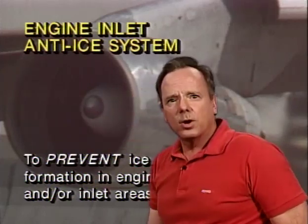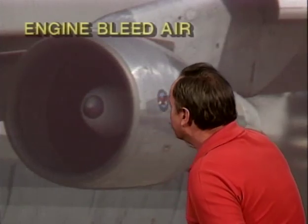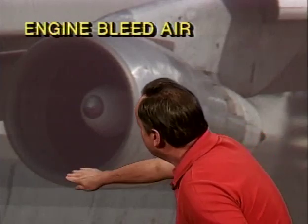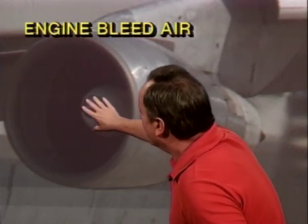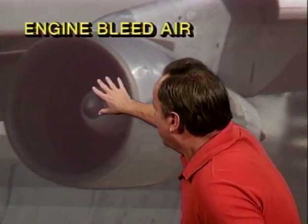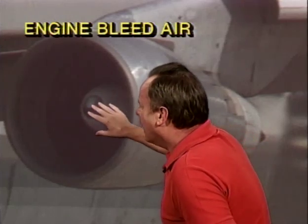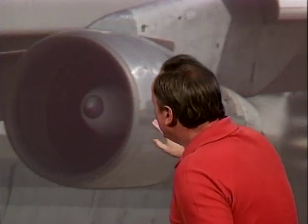Now, how does this work? Well, normally anti-icing of jet engine air inlets is commonly accomplished by engine bleed air. You take engine bleed air from the compressor, it's hot, you run it up here to the dome of the engine, the air inlets here in this lip of the engine, and that heats it up, and again, you're talking anti-ice, and you're preventing ice from forming on the engine. Now, when you do apply this anti-ice, you're going to get some change in your engine readings.